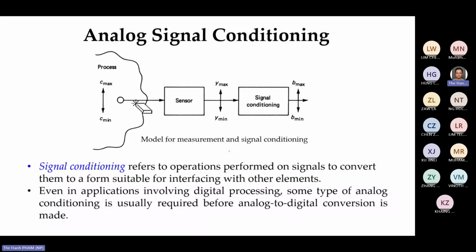It is because the typical arrangement or structure of the measurement system is this: this is what you want to measure, right? What you want to measure may not be electrical. It can be temperature, it can be humidity. Then you have a sensor, and this sensor will provide you with an electrical signal. It can be in the form of voltage, current, or varying resistance or capacitance.